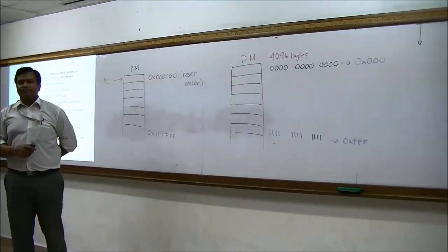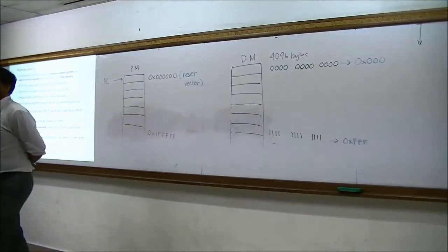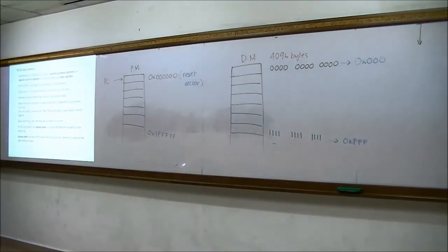Okay or not okay? The same thing applies to the data memory. What I want you to know is that the capacity is 4096 bytes, which means you have 4096 locations, and to address each location uniquely in binary, you need 12 bits. So you have this range, which if you represent it in hex, goes from hex 000 until the maximum hex FFF. Is it okay?